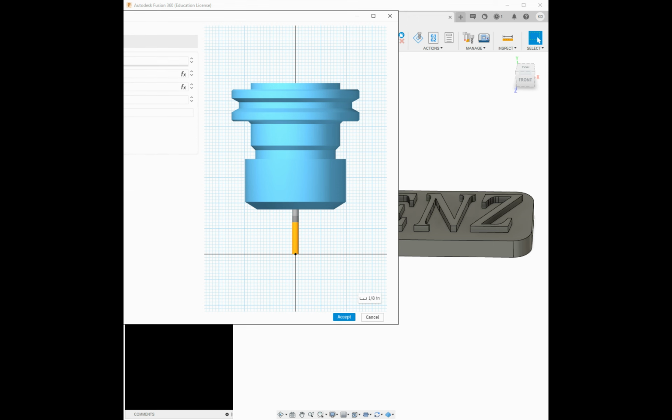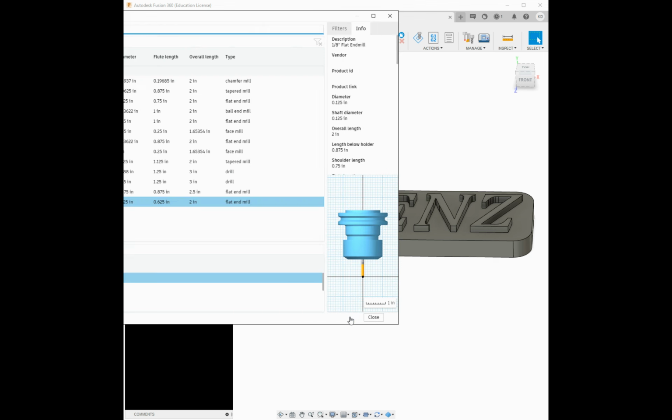Do go to Post Processor and make sure that you give it the right number. If we're using a tool changer, you need to assign this to the right place in your tool holder, or the machine's going to grab the wrong tool and you're going to have a big problem. So for our setup, our 1/8 inch was actually tool number 2, and turret number 2 in our changer. I have some options here as well, but we're not going to go into that too much. Click accept, it brings you back here. You can double check that it changed it, and then you can close it.